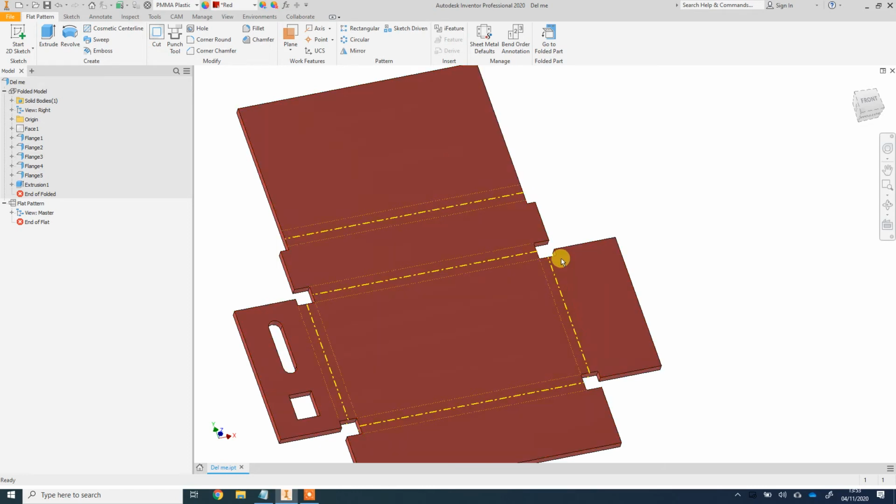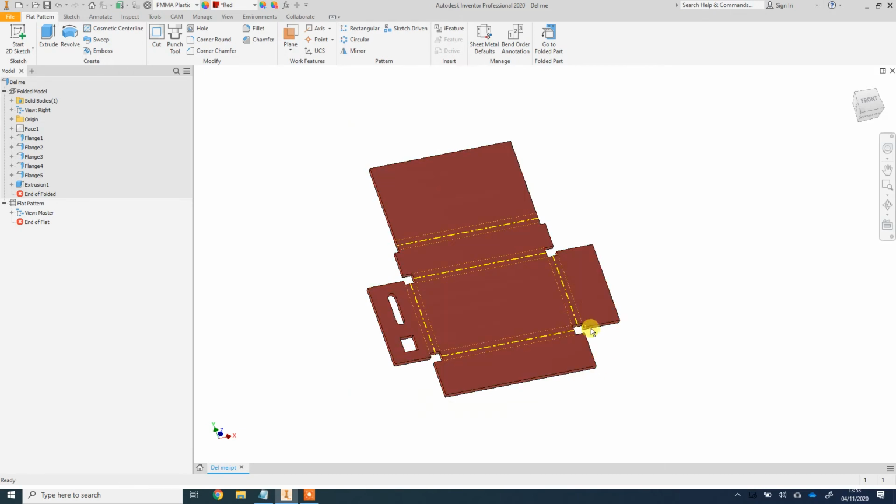Now we can't laser cut sheet metal, but if you wanted to fold an accurate metal box, what you could do is spray paint a piece of aluminium with a coloured spray paint, put the aluminium in the laser cutter, engrave all these lines through the paint into the aluminium, then use those lines to cut out with the guillotine and with the hand shears, and then use the sheet metal press to fold them around those corners. So there are ways around it if you want to work with metal at school.